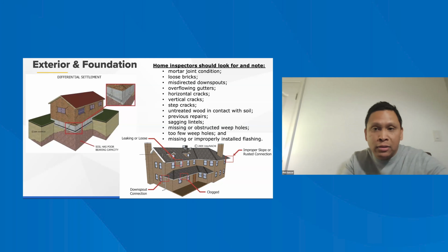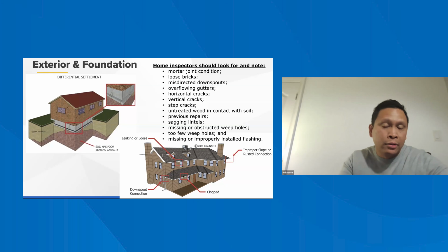Vertical cracks and step cracks are things that you want to note. Now, remember, not all cracks are necessarily structural cracks, right? Concrete cracks, that's just what it does. But we need to make sure that we identify and bring to the family's or the client's attention where these cracks are located. Is it our job again to determine why there's a crack here? No, but as we become more seasoned, we're able to help better assess and determine what the possible cause is.